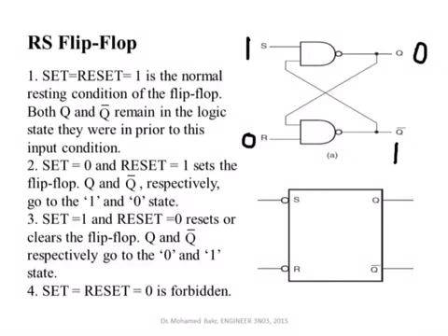Okay? Now the last condition, or the last state, is when you have the set and reset both equal to 0, which means you want them both to become active, and this is forbidden. This is a case that should not happen, because it will result in conflicting conditions in your logic gates. Because if you have 0 and 0, this means that this will become 1 and 1, okay?